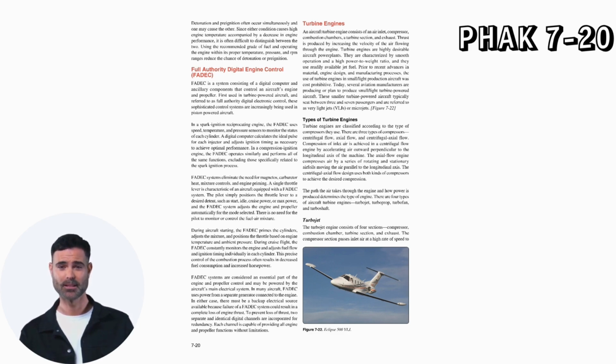Full authority digital engine control, FADEC, is a system consisting of a digital computer and ancillary components that control an aircraft's engine and propeller. First used in turbine-powered aircraft and referred to as full-authority digital electronic control, these sophisticated control systems are increasingly being used in piston-powered aircraft.